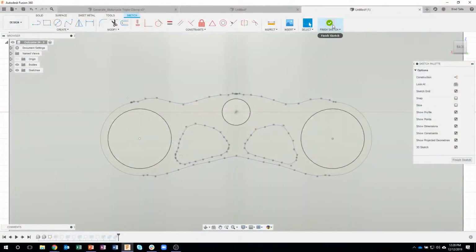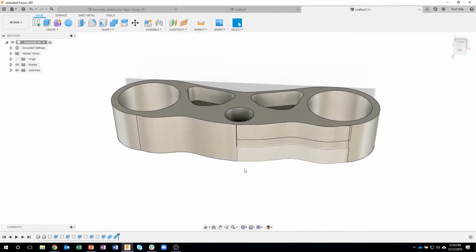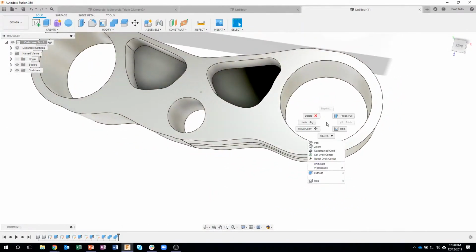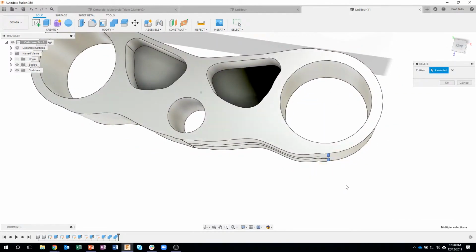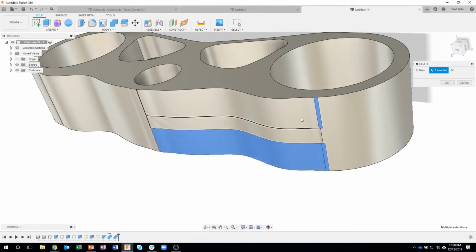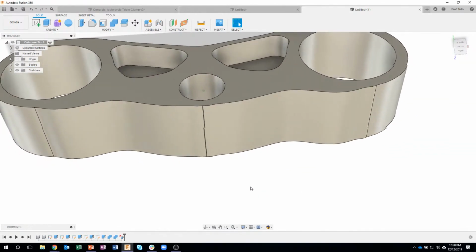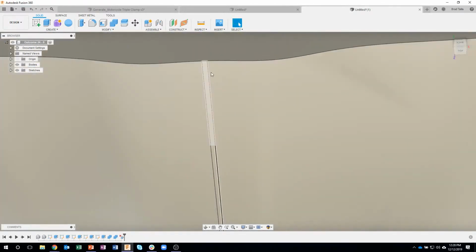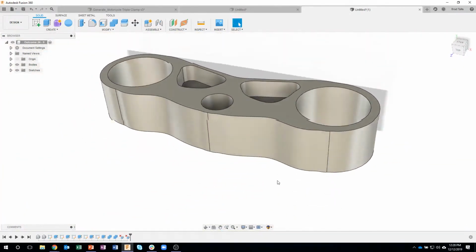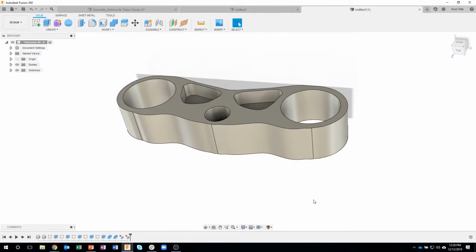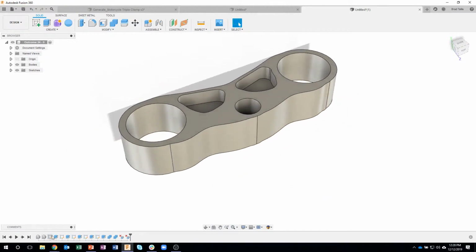And that's what I'm going to show in this example. So I'm going to leave these sketches alone for now, but there's some things on here that I don't like. So for example, I want to fix all of these regions here. So I'm going to just come in here and say delete, maybe just draw a box around all of that stuff, and maybe select these 2 faces and say okay. And you can see that I removed those extra little layers. Looks like there's a little tiny face here. I might just click on it, hit the delete key on my keyboard, and literally in a matter of seconds, I've now have a nice smooth representation that I could manufacture. So instead of having to edit the multiple sketches, I was able to just come in and delete some faces.